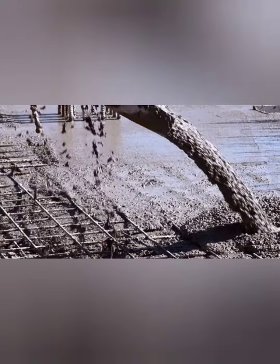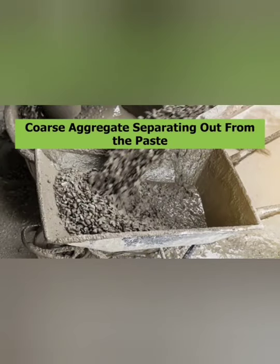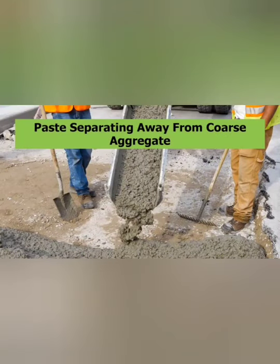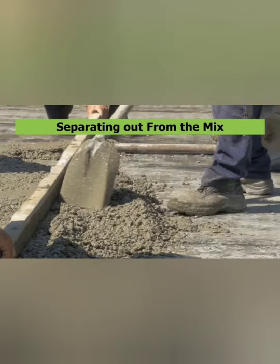In general, segregation occurs in any of three types. Firstly, the coarse aggregate separating out from the paste. Secondly, the paste separating away from the coarse aggregate. And thirdly, water separating out from the mix.